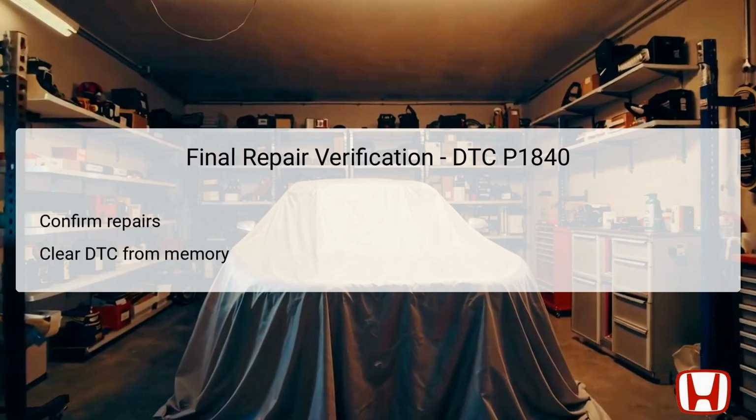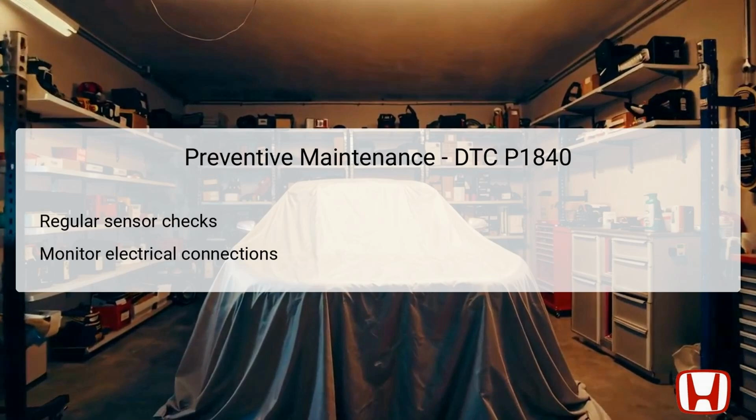with a reliable experience. To avoid encountering issues related to DTC P1840 in the future, preventive maintenance is imperative. Regularly checking the condition of the CVT speed sensor can help identify potential problems before they escalate into significant failures. Technicians should also monitor the health of electrical connections and wiring related to the sensor and TCM, as corrosion or wear can lead to intermittent faults and trigger DTCs. Keeping these components clean ensures that they operate without interference.